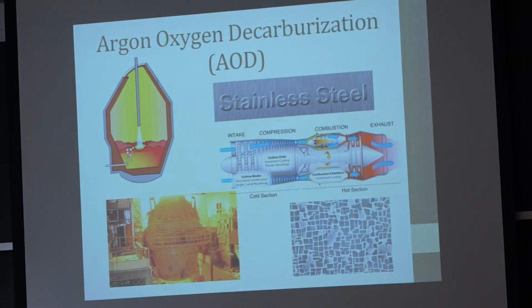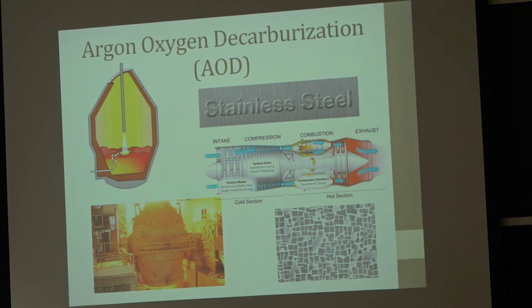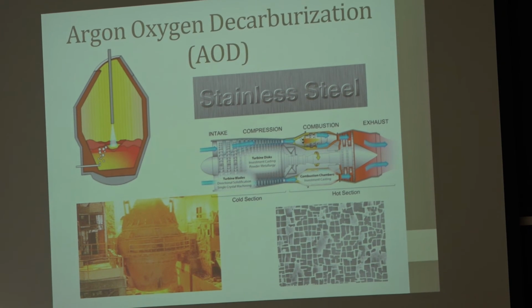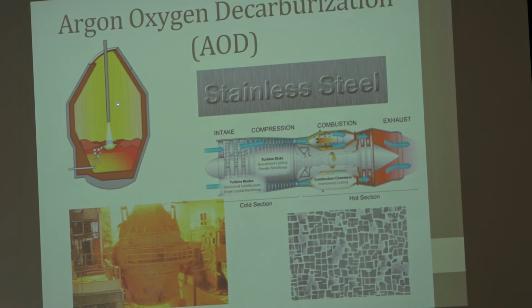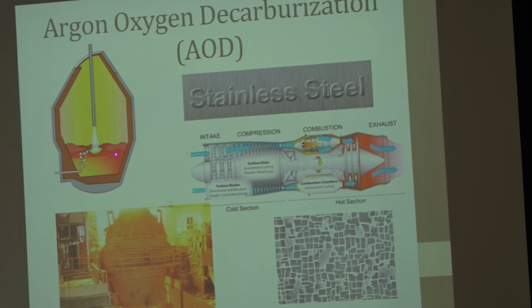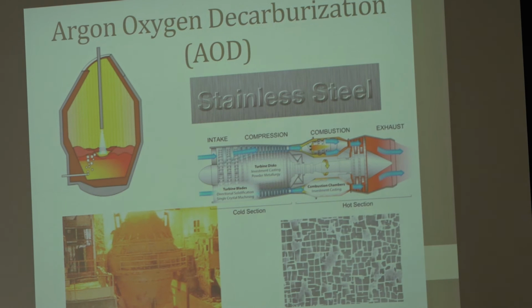Anyway, one technology which was innovated, the seeds of it were right in the basement of Building 8 here. It's called Argon Oxygen Decarburization, or AOD. The professor who worked on it was John Chipman. He had a student named William Krefsky, got his PhD. He was blowing argon bubbles through a bath of steel to look at the carbon monoxide reaction at different partial pressures of carbon monoxide.